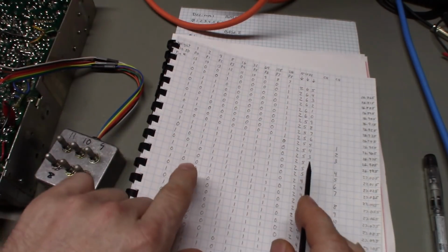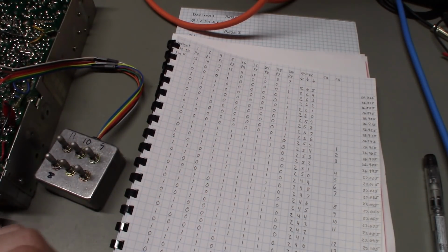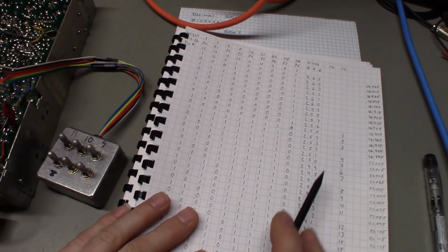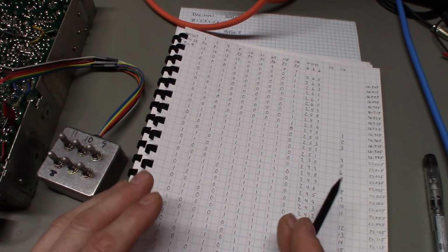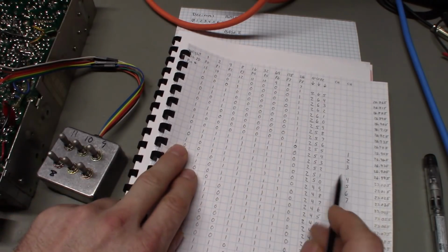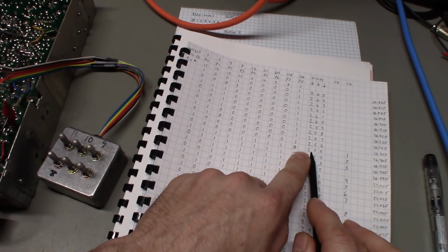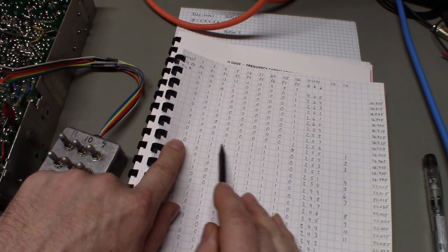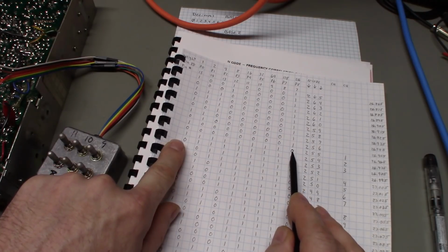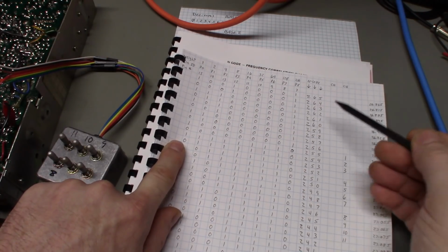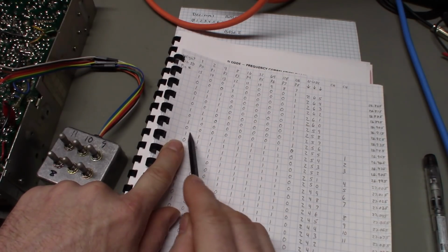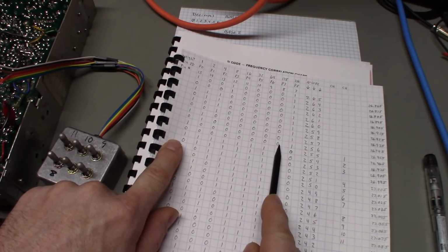Now, this is actually a good radio to show where low channels are really hard to get in easily, I should say. If you look at the code, and this is something to look at when you're trying to do a channel modification, you're looking for similarities where there's a lot of the same thing. So if you look at what channel 1 is, that's binary code 255. That's, like I said, all ones except for the most significant digit is a 0. Remember, the encode counts backwards here compared to the channels. So if you go -1, look what that did. All zeros and a 1.